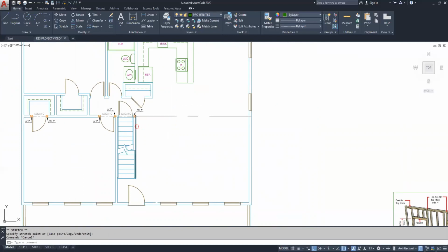Now I'm going even further, so this header is going to be even bigger, which means deeper. If the client or the designer doesn't want that, that can be a problem. These are what we constantly battle as we're trying to design something. How deep is this beam going to be? Is that okay? Can we work it into the design, or do we figure out another spot to post it?